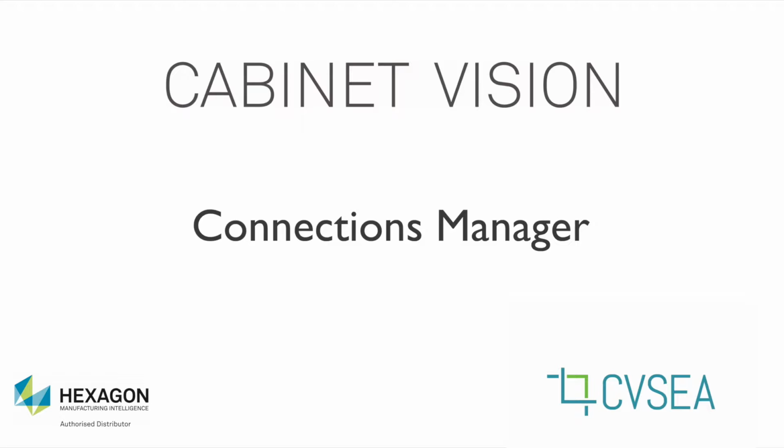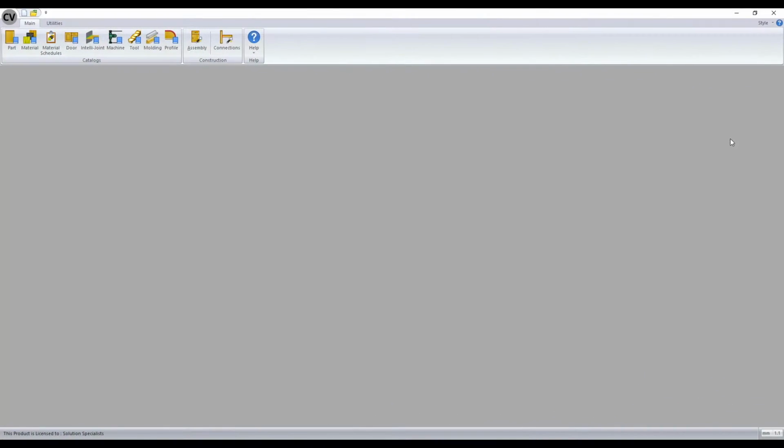One of the biggest changes in Cabinet Vision version 12 is the addition of connections. A connection is a group of operations that can be applied to the joints of your assemblies. There are two steps required to use these new connections within your assemblies. The first is to create the connections within the Connection Manager. The second is to apply these connections to the various joints of your cabinets by choosing them from within the